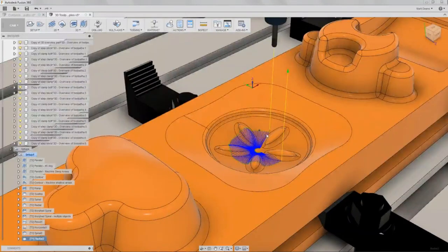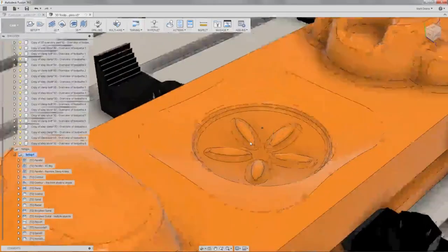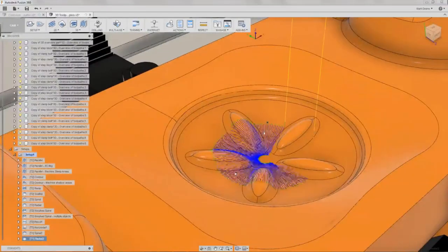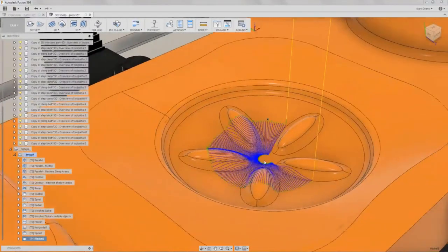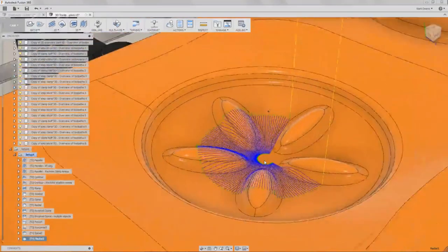So it's starting at 20, going all the way to around 270, taking a 2 degree step over, starting 0.1 inches radially from the center point, going out to 0.75. So I used a lot of the options there that maybe I wouldn't use in real life. I'd probably have it go all the way around, things like that. But those are the options with radial.